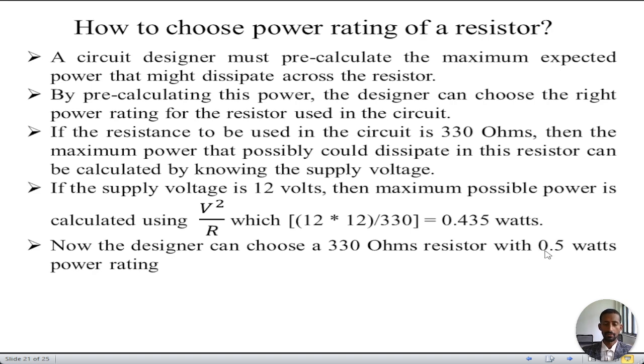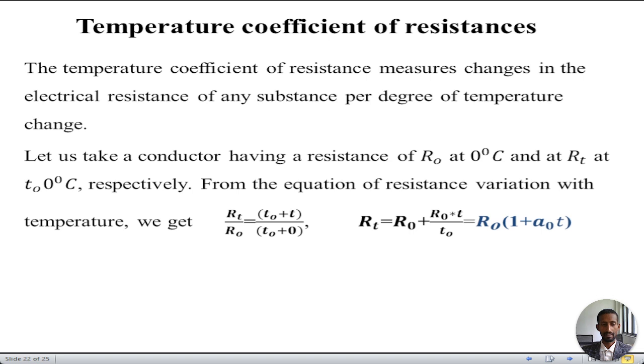the designer should select a 0.5 watt power rating for the resistor. If you have misselected the power rating of a resistor, it will malfunction. It will not properly work. So you should take care of the power rating of your resistor while you are buying from different markets.